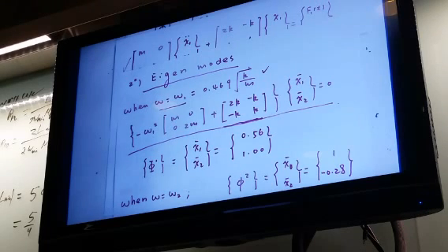Those two values are the vibration magnitude. So this is the first so-called eigenmode corresponding to the first eigenfrequency. If you use omega 2 in that matrix, you can get another relationship, another ratio between x1 bar and x2 bar. This is the so-called second eigenmode, another eigenvector. When you have 2 eigenvectors, you can form the total phi matrix.